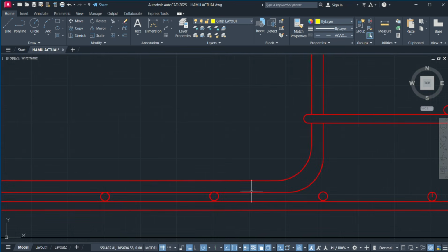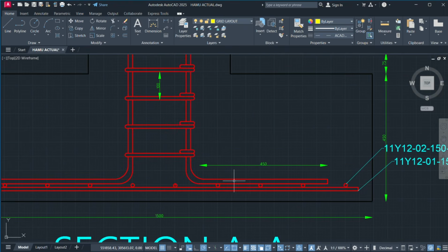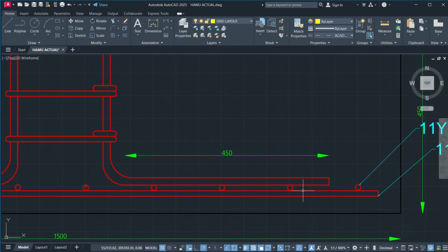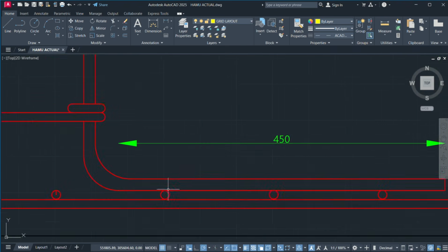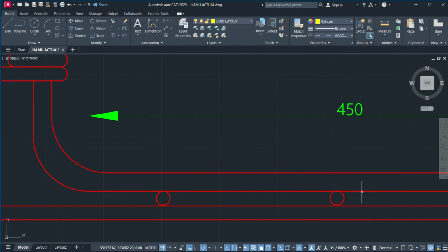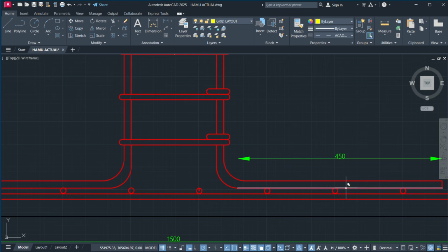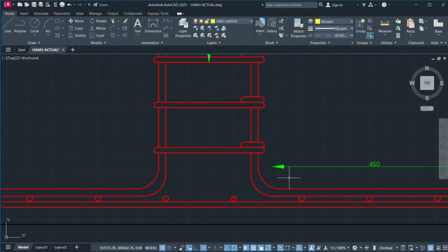Now, on top of these two balls, you need to offset from here, going all the way up to the top. That's if you want to use offset, for example. You're going to need to offset by a distance of what? 12, because these balls are also going to have a diameter of 12. Now, your line needs to touch exactly on top of these rounded balls that you've created. Then you offset this line again, coming up to a distance of what? 12 again. That's how you get it.